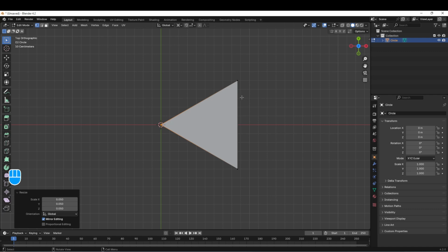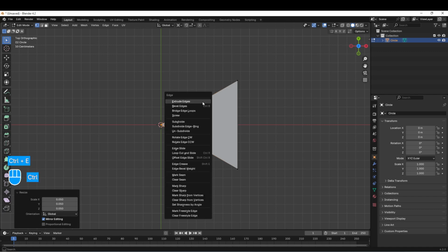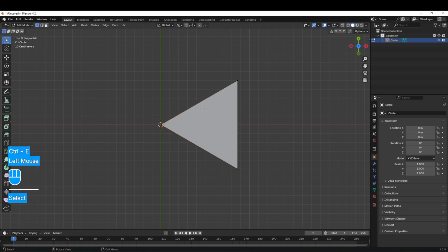And to create that, we're going to divide this with 3 loop cuts. So I'm going to put my mouse here at the top center, Control R, sorry, I hit the wrong button there. Control R, roll my mouse wheel up 2 more times, so we have a total of 3 lines. Then double left click to confirm that and to place it. Now we'll have 1 at this point, we'll have 2 here. Then for this one we should have 3, so I'm going to select this, and when I say 2, we have 2 vertices. We need 3 vertices here.